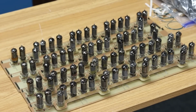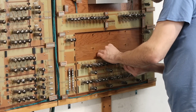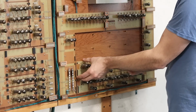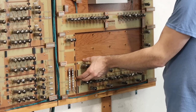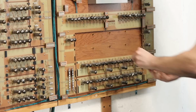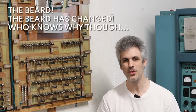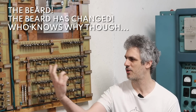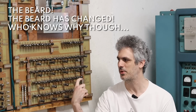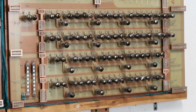And for those keeping score at home, the entire UE1 is now using a total of 324 6AU6s, 6 2D21s, and pulls around 675 watts of filament power. We're all back together now, and what has changed and why? Well, the only things that I've really messed with are the scratch register and the output register. This is our 8 bits of random access memory and our 8 bits for output.